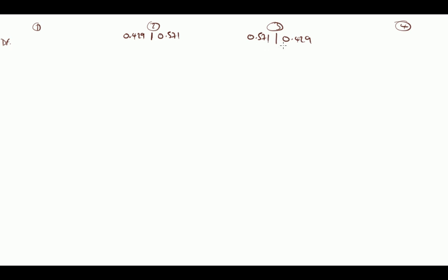So any imbalanced moment here needs to be distributed, and it will be distributed to the stiffer side of the joint. So more will come into this side than this side, and similarly this side will take more than this side for any imbalance of moment at that point.